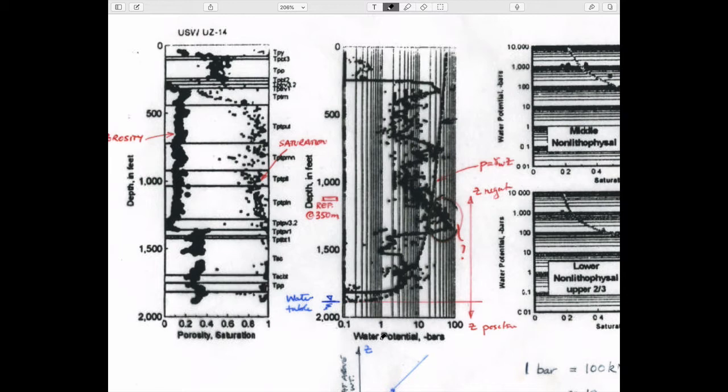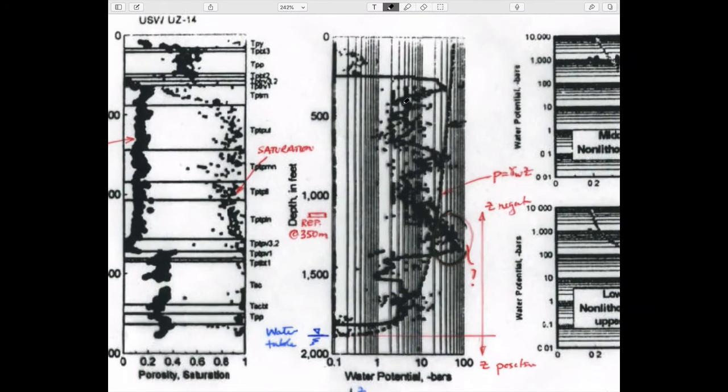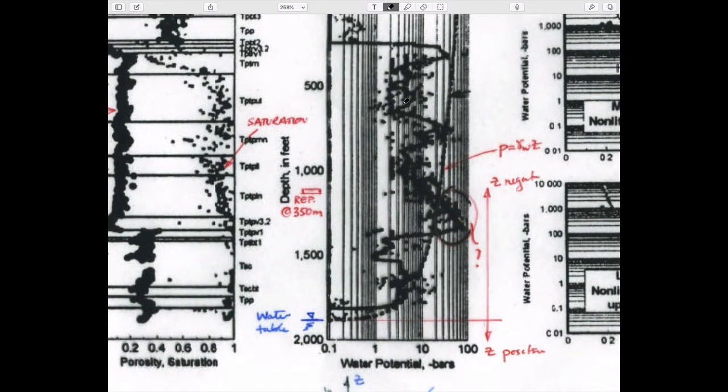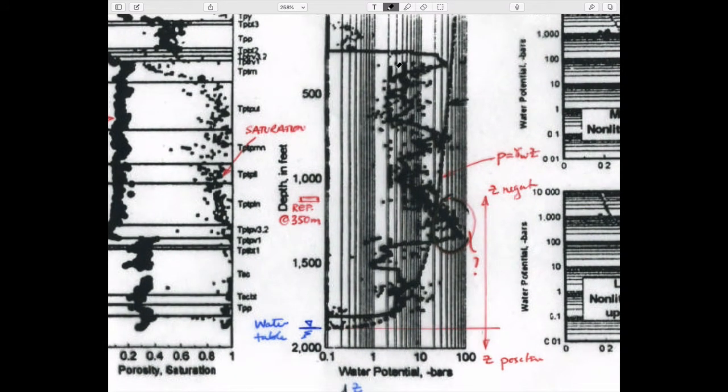And this is the capillary potential in the water as you go down through the column. It's a really scrappy diagram, but you get the picture. Each one of these dots is a data point. One core sample, which has been tested to measure the pressure within the water. There's lots of air pressure within those samples, mainly air, but the water is present at some low saturation.